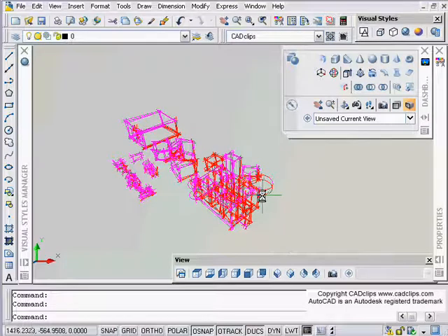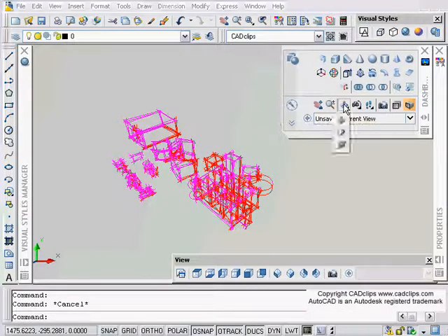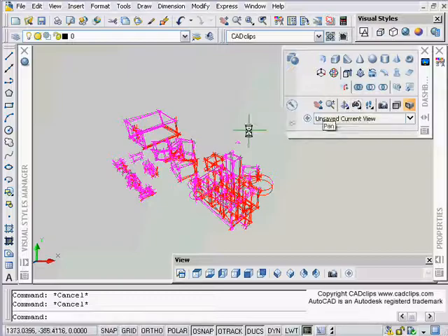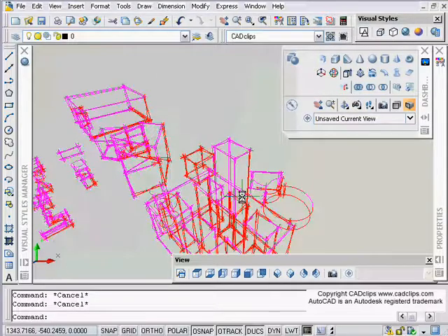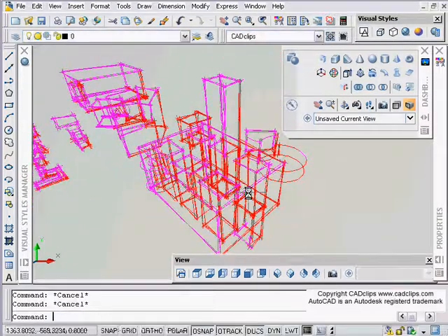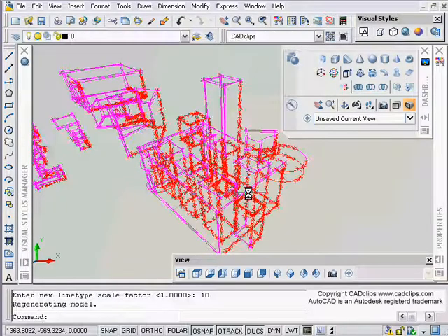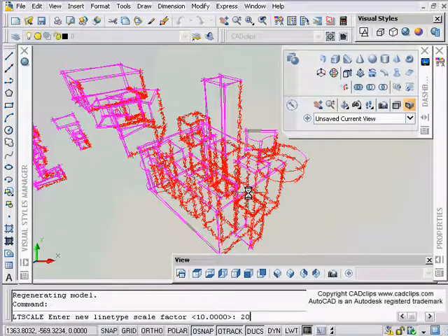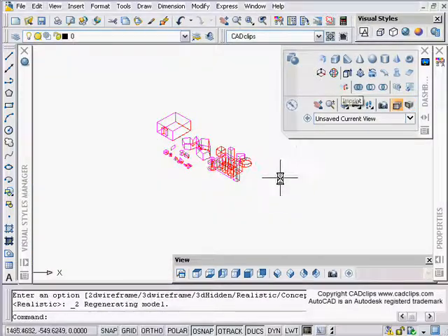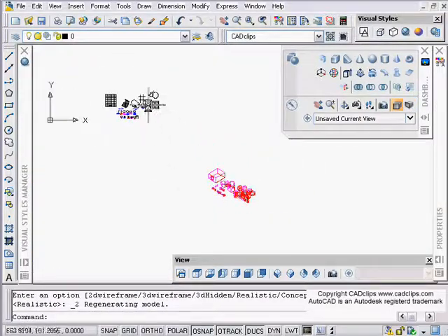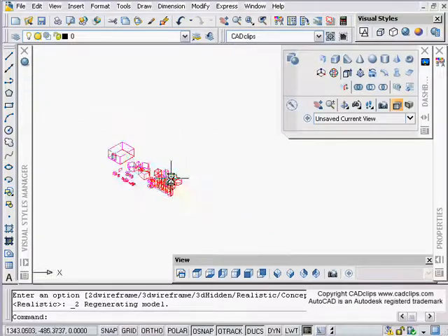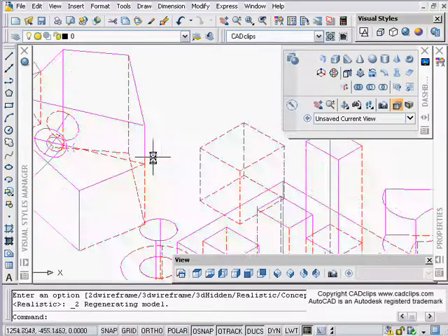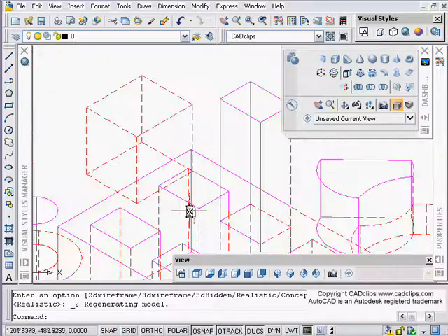Okay, now I probably want to get rid of my perspective, right, by going and starting my command. Okay, now the thing is, I'm not seeing these as dash lines. I need to type my LT scale, probably change it to be 10, maybe 20. Maybe I'm going to change back to be wireframe instead. Okay, there's my top view again. This is the block I'm playing with that was created with the snapshot, and there's my dashed lines,